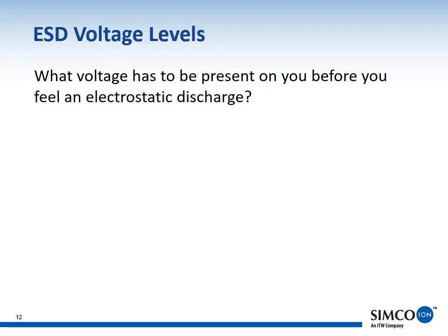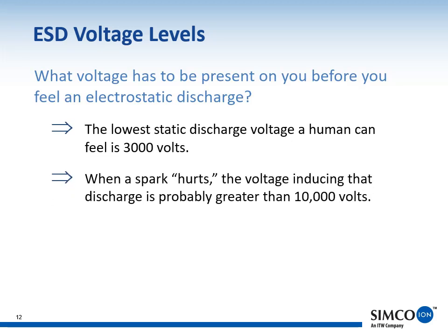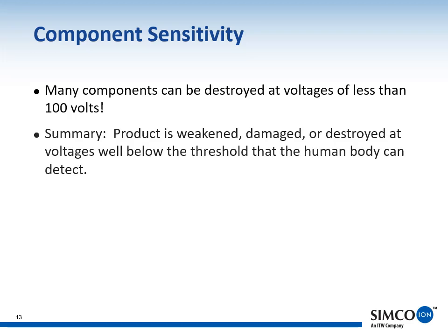The human body cannot feel discharges less than about 3,000 volts. If the spark hurts, it's probably well over 10,000 volts. However, many of the components we are handling in our production areas will be damaged at voltages well below 100 volts. So this means that we can be damaging or destroying components without even being able to feel the ESD events occurring.